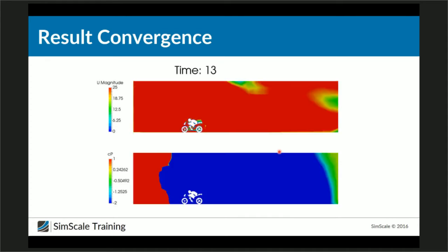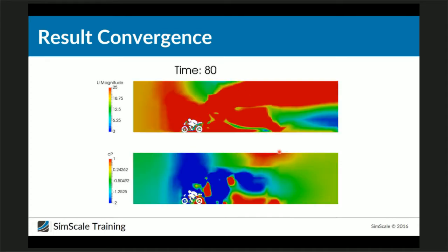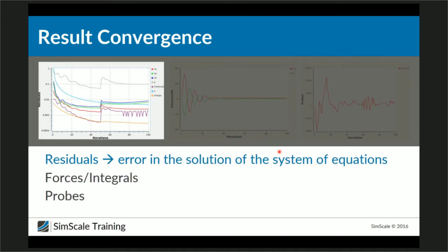And now I would like to talk with you about convergence. That's a very important aspect of CFD. Like most numerical methods, in CFD we have an iterative approach, which means we start with a rough solution, and we iterate until it becomes more and more accurate. This also means that you have to be careful, because CFD can also mean colorful desktop, nothing more or less than a bright picture.